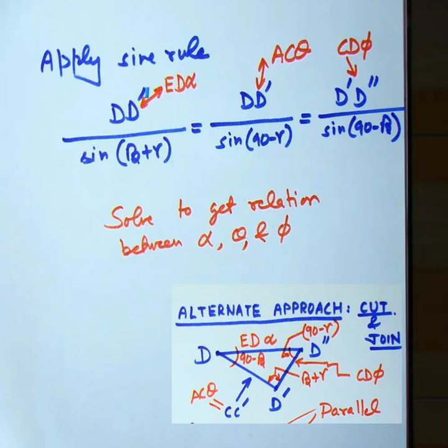We can then substitute the values of these displacements in terms of the angles alpha, theta and phi, and we already have the relationship between these angles. So then we can solve this equation and get the solution. We can solve the equation of virtual work, and based on that we can find out the ultimate load for this particular mechanism. So this is the alternate method.